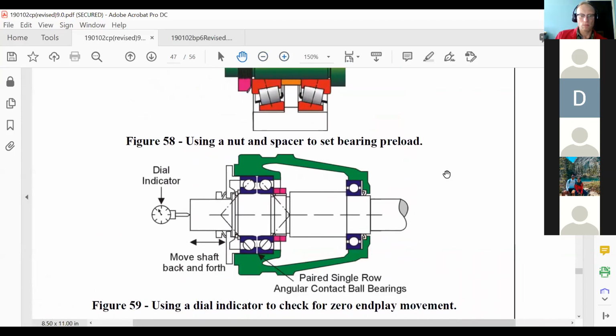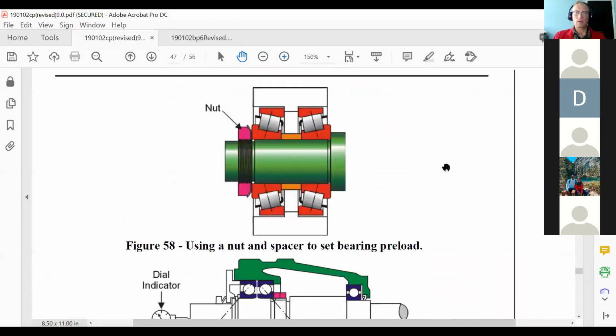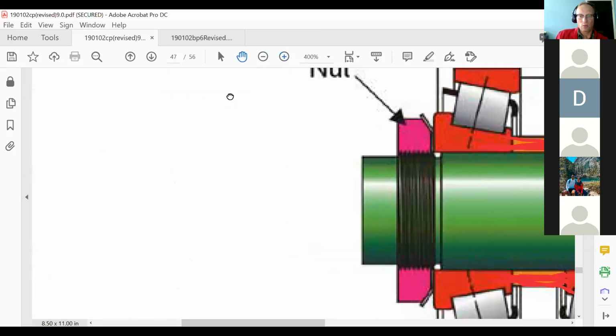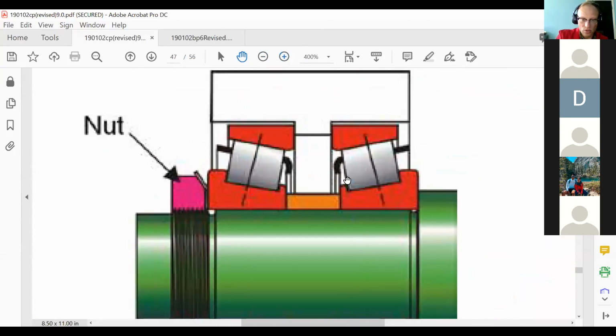They have those cones now too, so now they're kind of dumb proof. Oh yes, the spacers. And if you look, I didn't talk about it, but there is one right here. No one else mentioned it either, and I was happy because I could talk about my example, but now that you pointed it out, I'll mention it. What this spacer is actually doing, this orange piece, is stopping these two races from coming any farther together. So essentially, you tighten this nut up to a certain torque value, and the end play should be set. It's just a matter of you measuring it to confirm it.